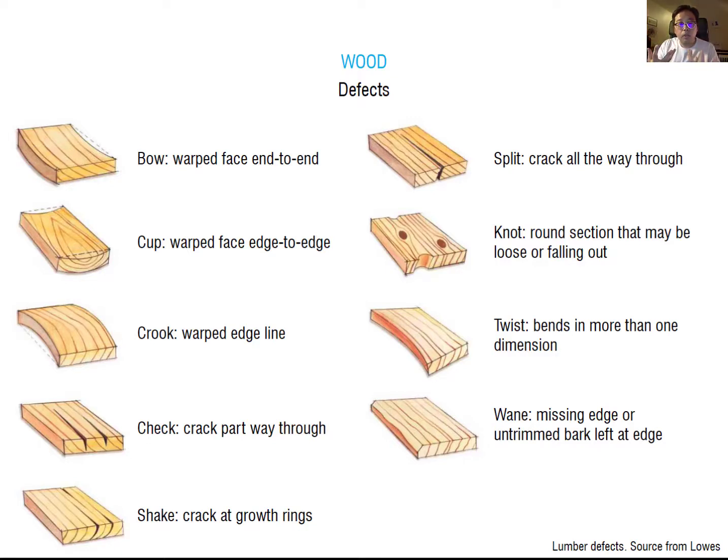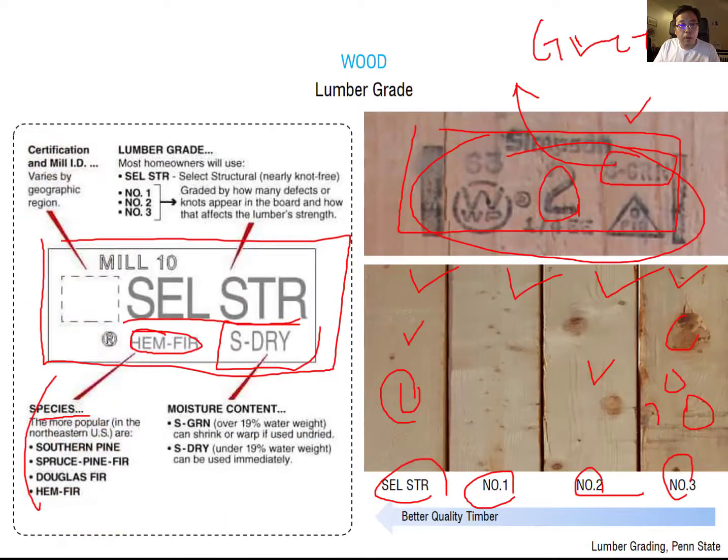And if it contains water moisture, it is usually easy to bend. So when you're using timber, you have to choose your timber product very well. You have to check the grade label to choose your timber product properly for your design.